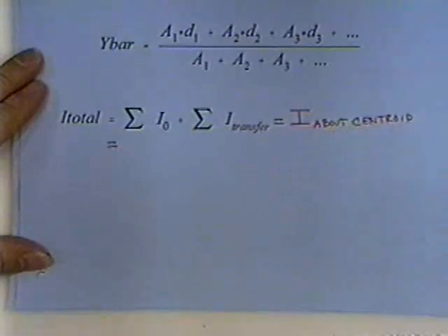That's because everything always tends to bend about the centroid. When you took ME 212 or whatever, they made you find a moment of inertia about the base, moment of inertia about 2 feet up. Well, those were good practice, but you don't make any money with those. The one that is worth something is the moment of inertia about the centroid of a shape.